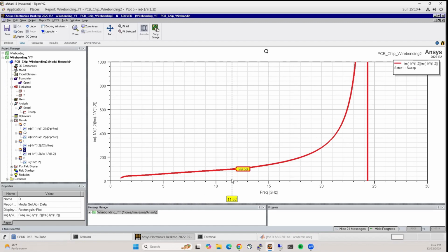So even the Q is not really valid beyond that, right? And you expect the Q to go up with frequency as long as we have just a constant inductance because it's omega L over R, where omega goes up linearly with frequency and R goes up quadratically with frequency, right? So Q should go up quadratically with frequency. Quadratic, as in, sorry, not quadratic, square root. R goes as a function of square root of F, and L goes as F, so Q should go as square root of F. Okay.